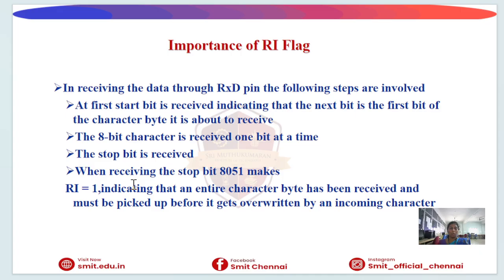How will you know the data reception is complete? Yes, when the RI flag is set to 1. So the RI flag is set to 1, and all the data loaded in the SBUF register should be received. That is the main theme of the RI flag.